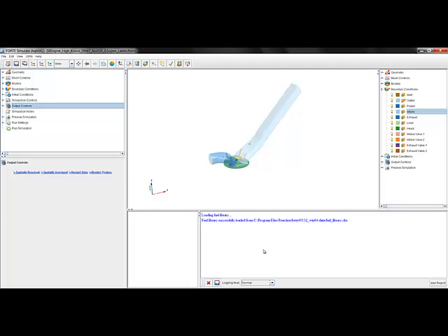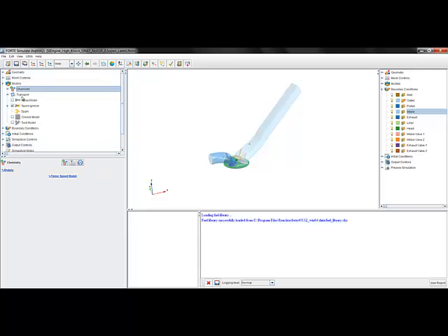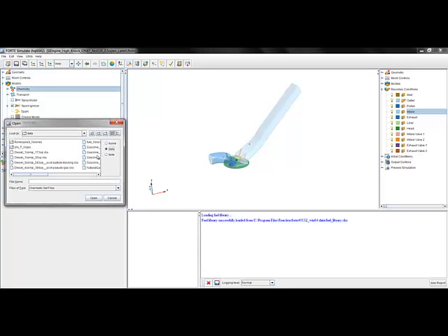The next step is to specify the chemistry mechanism we want to use for the simulation, which is really determined by the fuel of interest, whether it be a gasoline or a diesel fuel or a dual fuel type engine. There are several fuel models available with Forte. In this example, we're going to use a gasoline PRF fuel model, which consists of isooctane and N-heptane as the fuel components. The fuel composition used provides an octane number of 87.